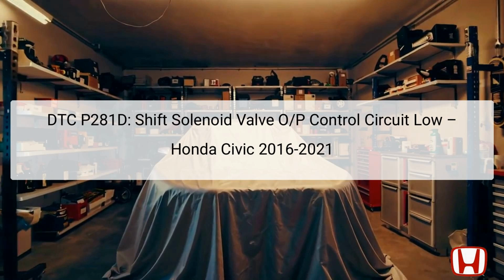The solenoid's primary function is to control the opening and closing of the drain circuit, as commanded by the Transmission Control Module, TCM. Located within the transmission assembly, the shift solenoid valve plays a critical role in ensuring smooth gear shifts by varying fluid pressure based on operational demands. The TCM commands the operation of this valve and monitors its feedback through the control circuitry. If there is a discrepancy between the expected and actual signal received, the TCM will flag this as a malfunction and store the DTC for future analysis.